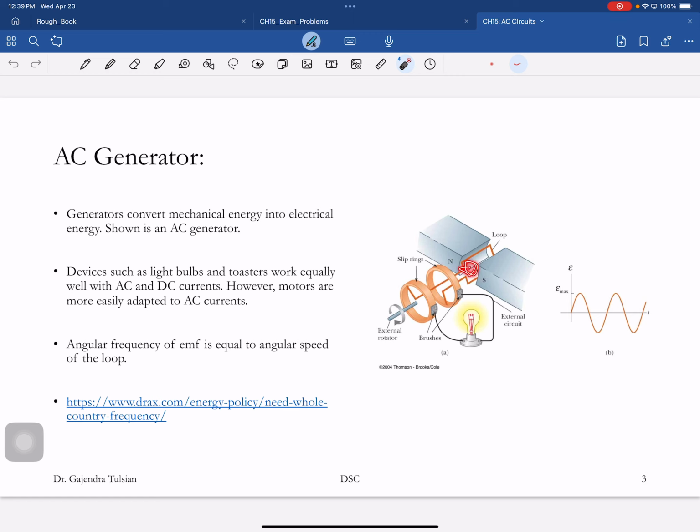And if this wire is turned 100 times a second, you get a voltage whose frequency is 100 hertz. You can change the amplitude of this by increasing the area of this coil, by adding more turns to the coil, and so on. But the frequency at which you turn this coil is the frequency of the AC signal. And it's a sinusoidal voltage that you produce.